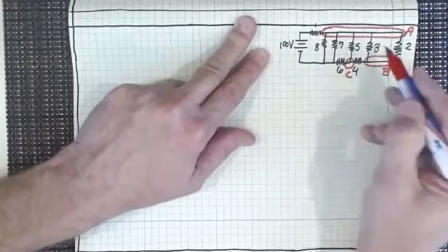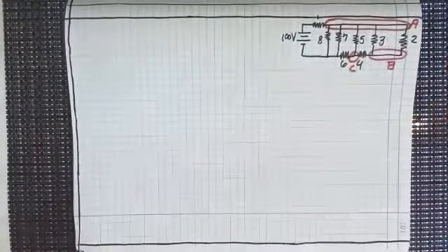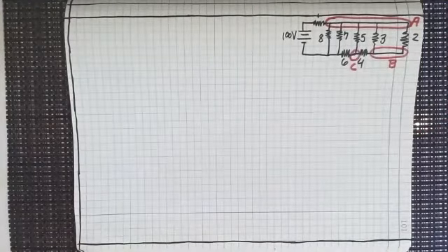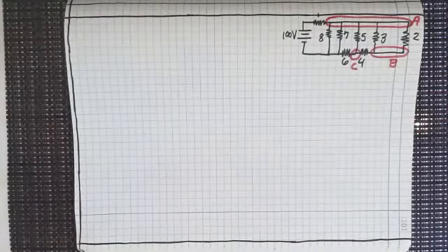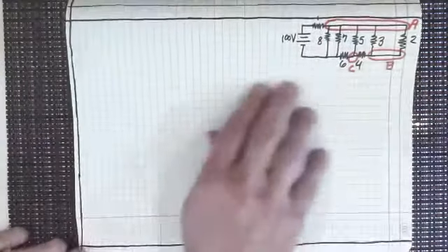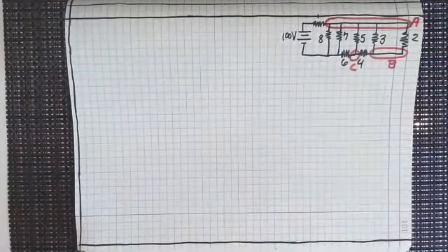And then all of the other resistors that were attached to that very complicated looking circuit, we just worked out what was in parallel, and we expanded the node out where we had a lot of connections. So I think everybody saw how I did that.